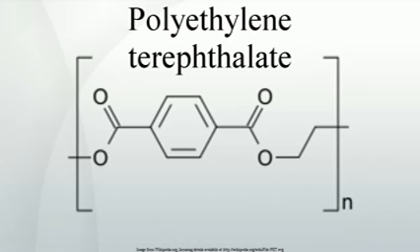On the other hand, crystallization is important in other applications where mechanical and dimensional stability are important, such as seat belts. For PET bottles, the use of small amounts of isophthalic acid, CHDM, DEG or other comonomers can be useful. If only small amounts of comonomers are used, crystallization is slowed but not prevented entirely. As a result, bottles are obtainable via stretch blow molding, SBM, which are both clear and crystalline enough to be an adequate barrier to aromas and even gases, such as carbon dioxide in carbonated beverages.